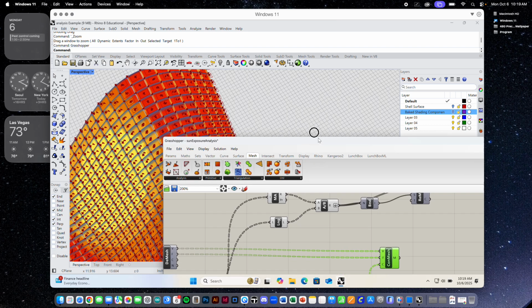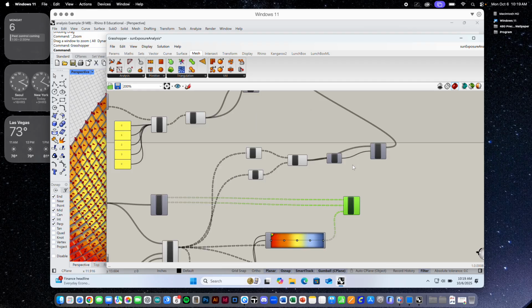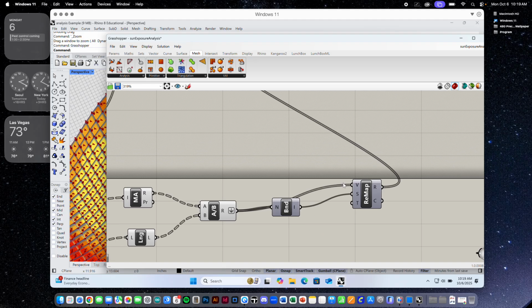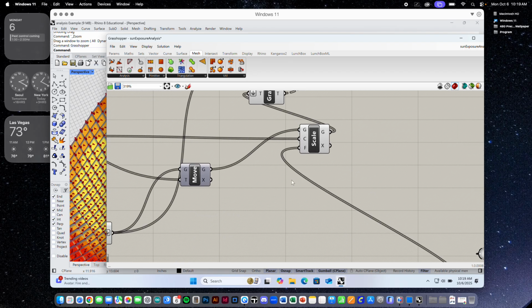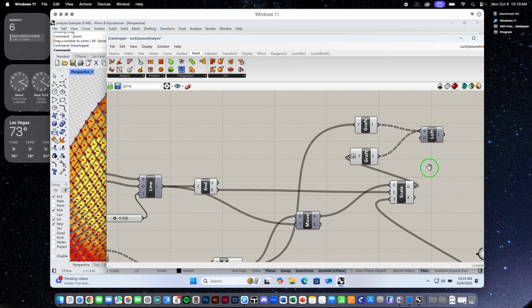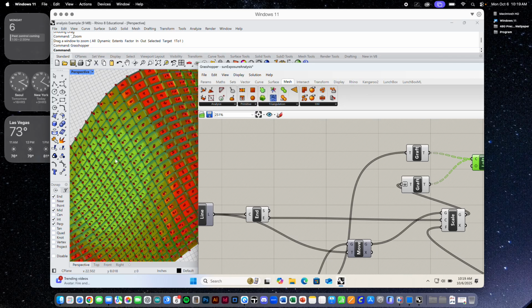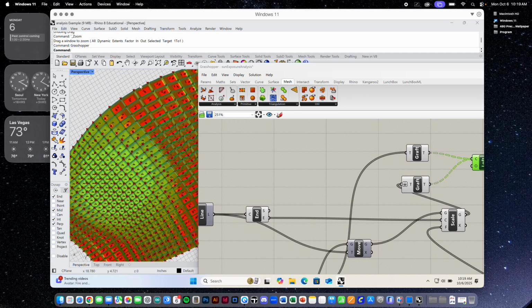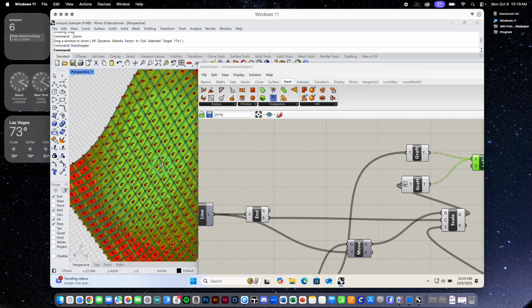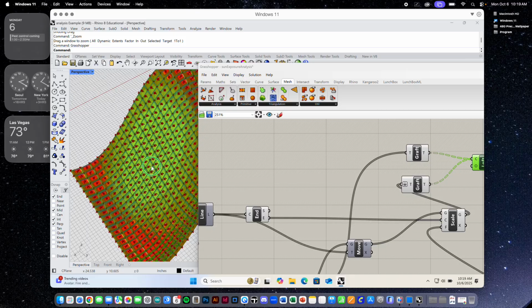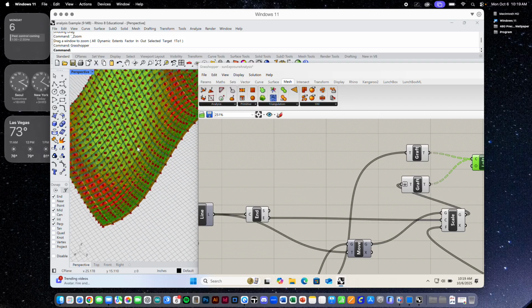But once we have those values, we can also remap them to any sort of minimum and maximum we want for, let's say, the height or the opening or the UV parameter for each of these shading components, scale or loft or open or close accordingly in order to generate a set of components that are more open or less open depending on the values, right? In a gradient fashion. So that's sort of serial differentiation, right?